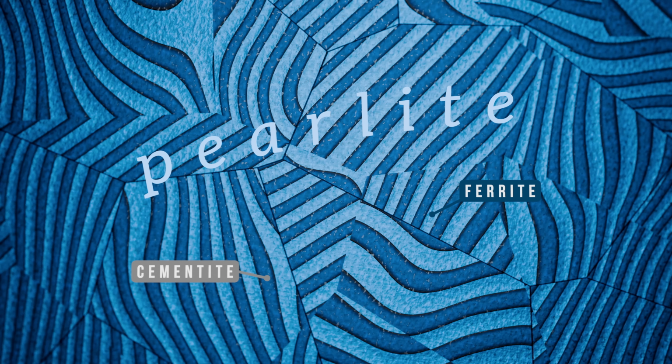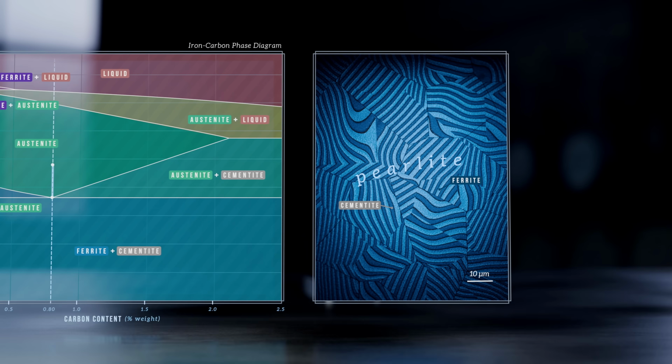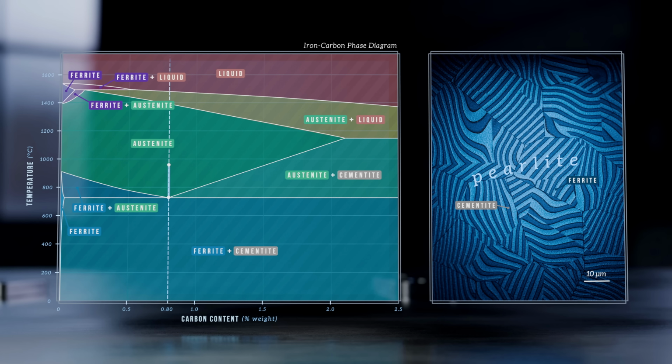This composition is a special case, because the austenite transforms entirely and simultaneously into ferrite and cementite, producing only pearlite. The point on the graph at which this happens is called the eutectoid point, and steel with the corresponding 0.8% carbon composition is called eutectoid steel.